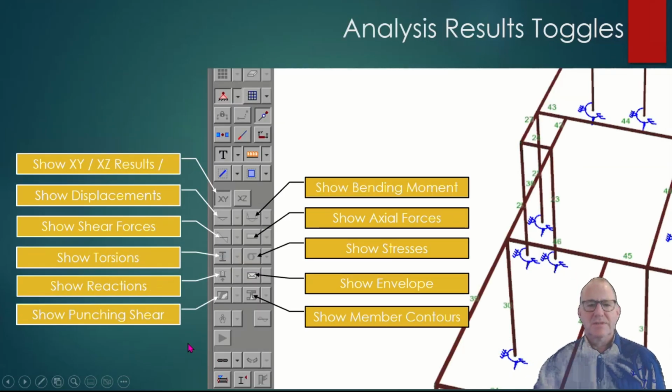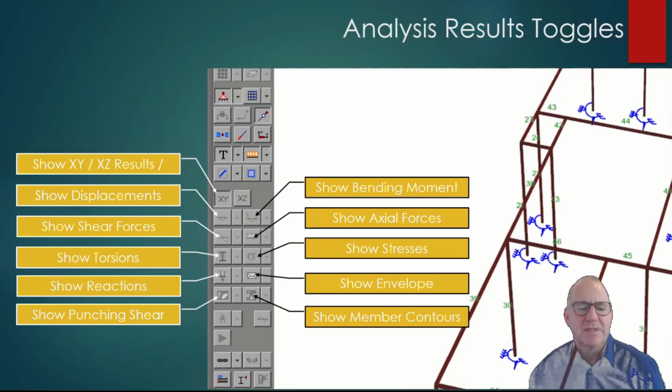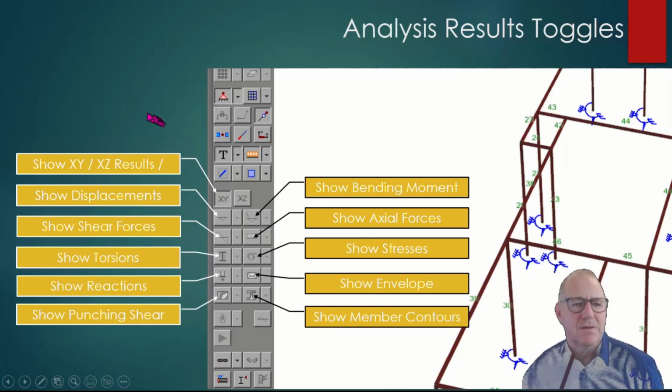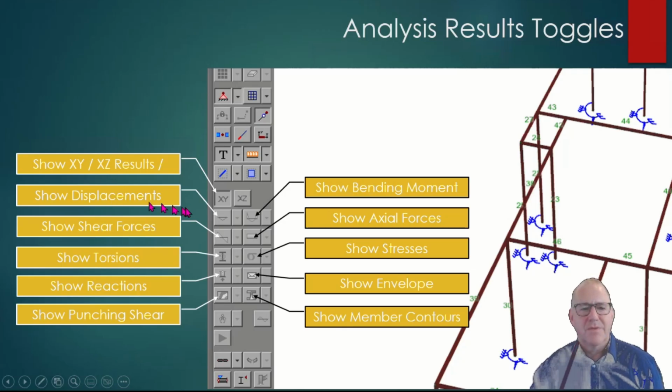Once you've done your analysis, you'll be able to look at the analysis results. So down the left-hand side again, you're moving down a bit more, and whether you're showing results. Now this is more important when you're looking at plates. Which plane are you looking in? Are you looking in the XY or the XZ plane?